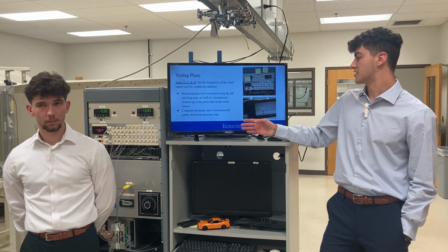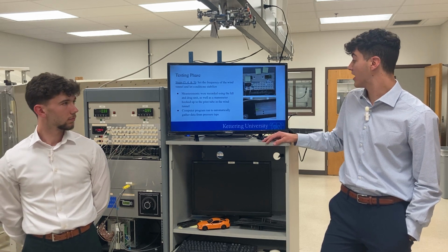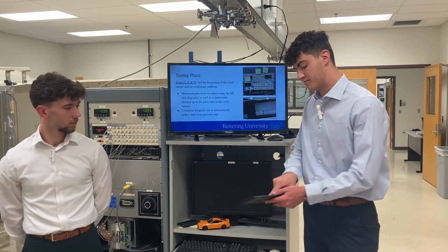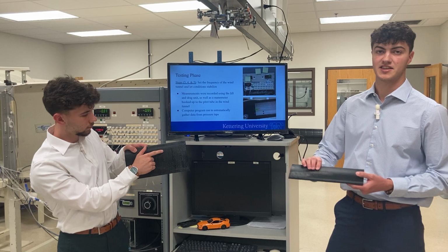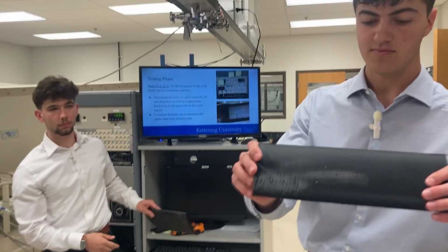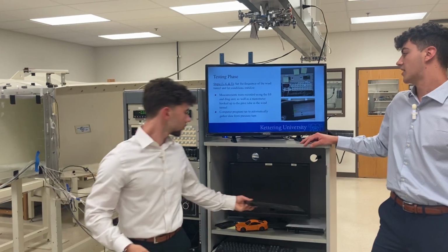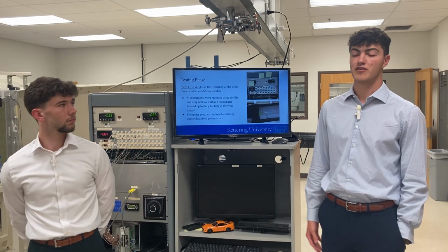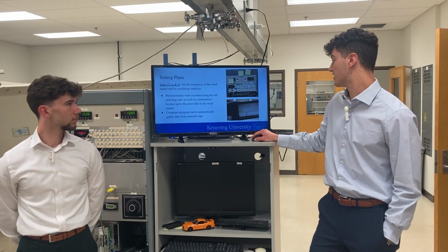So, like I mentioned, this machine was able to calculate the static pressure tap measurements for us, and although it has 40 some odd points for you to hook in tubes, we only used 2 pressure taps per airfoil, one closer to the front of the top of the surface and then one near the back to see if pressure would change as air flew across the top of the surface, if you want to get a close-up view of that. So we use data points 13 and 14, and this manometer back here. Since we had an issue with getting the stagnation point from our airfoil, we used the stagnation point from the pitot tube to basically use that as a replacement and solve for velocity that way.